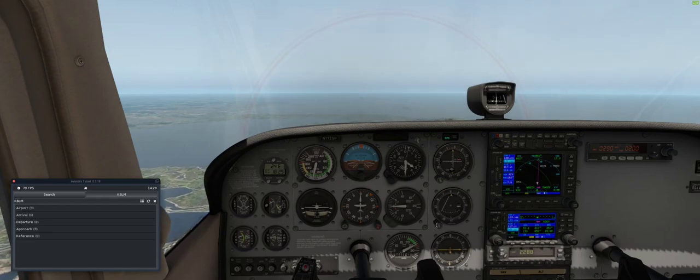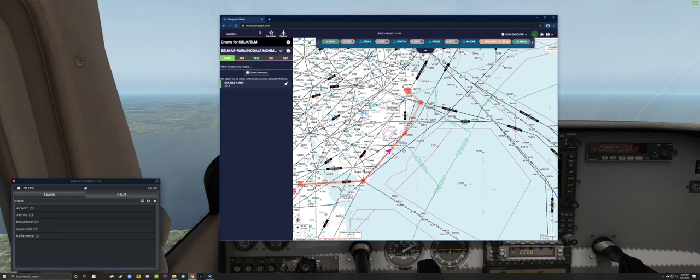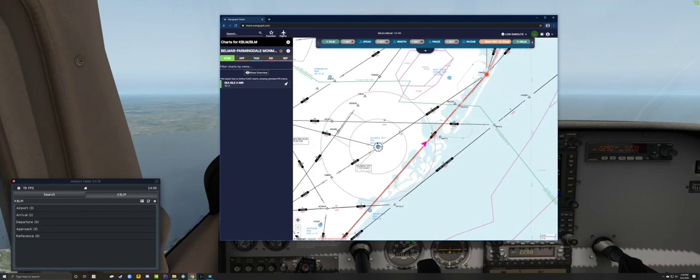And for a VOR, you can find where you're at relative to it by moving the OBS knob, because whenever you get to where that VOR needle centers and this flag points in that direction, it's telling us that this VOR radio is about 90 degrees from where we're at right now. If we look at a bigger map, yeah, it is. That's that VOR.